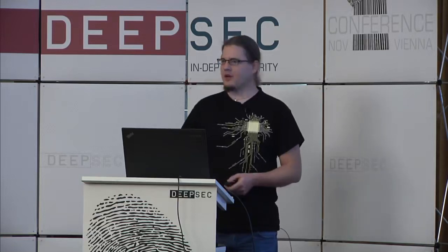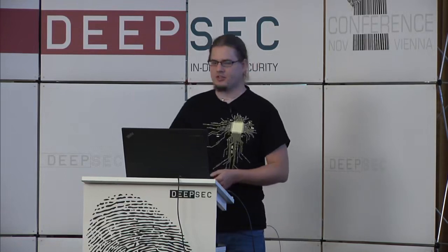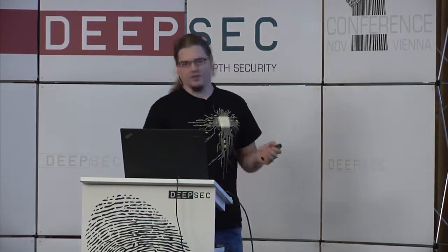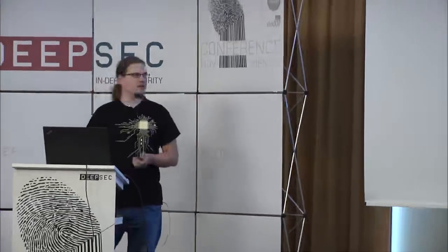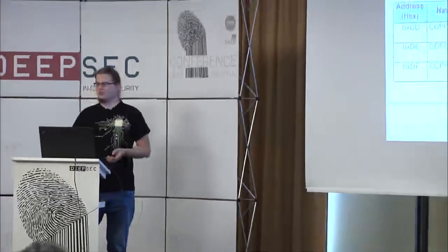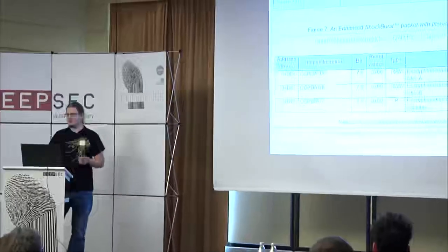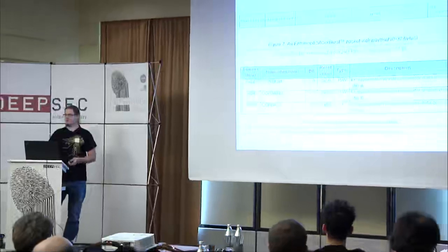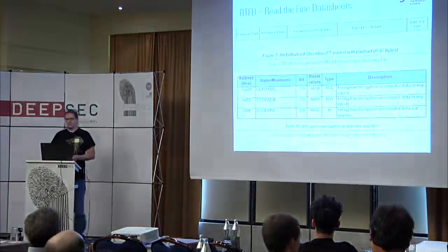You can have a look at the radio protocol too. The radio protocol is documented in the same data sheet. So everything you need, you will find there, how it is decoded. And another interesting thing, why it's easy to use encryption for that wireless protocol, is down here. These chips have an AES coprocessor to encrypt with high performance. And you don't have to implement your own AES encryption.